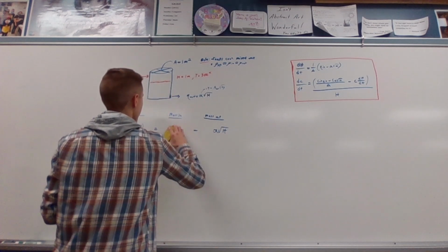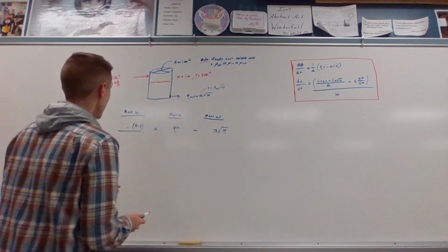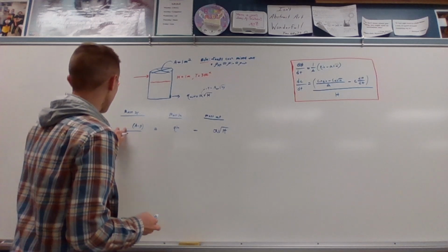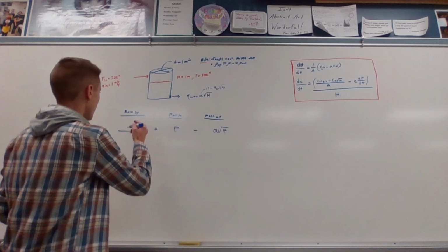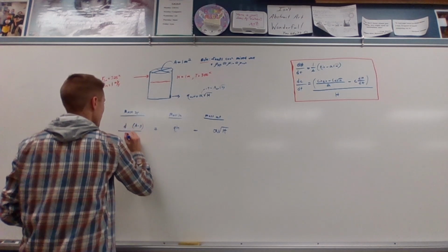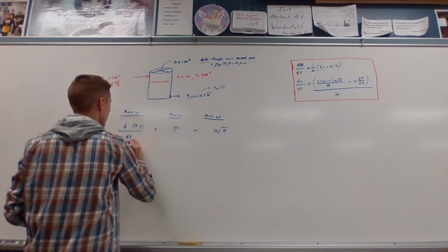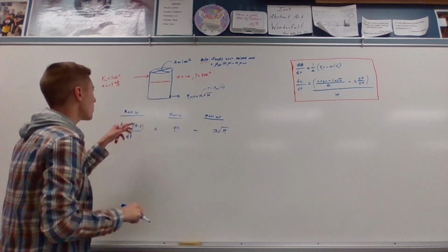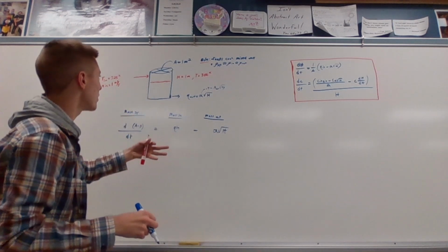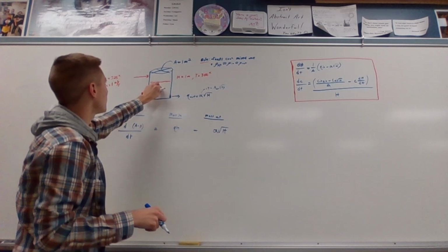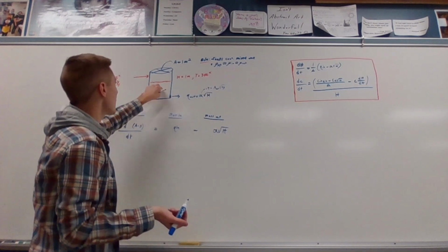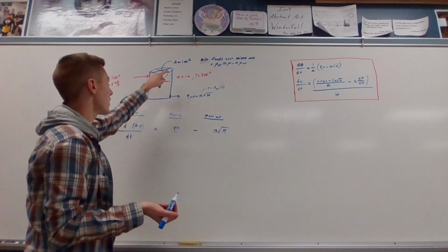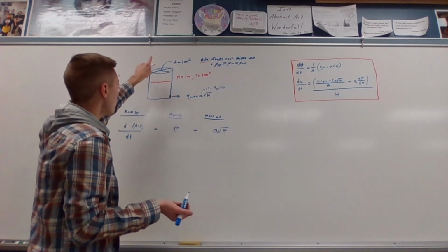All right, so now we've done that. We want to go ahead and take a derivative of this side and set it in terms of t. Another important thing to notice is that for this tank, we want to look for constants. Up here, we have two variables: our cross-sectional area and our height.